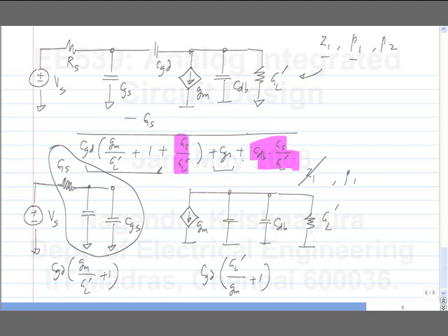If Gm by GL is very significant, then that's the dominant part, so we don't have to worry about other things. What about the output pole? I mean basically the pole P2. Is it the same in the two cases? Yeah, so actually if you do calculate the pole from this, it will be related to GL and CDB and CGD. Okay, it's not so much dependent on Gm. Whereas in the real analysis, we saw that it is predominantly determined by Gm. And why does this happen?